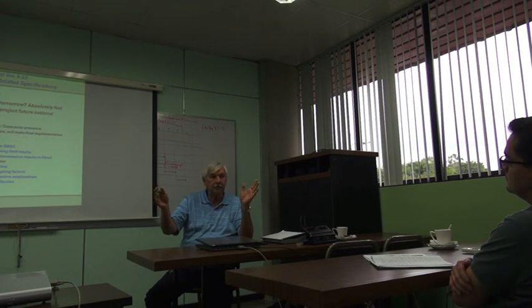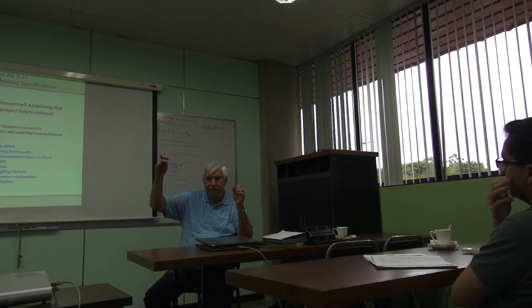Okay? If I wanted something that's going to last 20 years for fatigue cracking, I can convert what we actually build, the structure, into whether it's going to be 25 years, 15 years, 12.5 years. So eventually the final equation is going to be in terms of the predicted design life. Then the predicted design life is going to be a function of all of these things: the pavement structure, the E of the asphalt, the location, the temperature. The E in turn is going to be a function of the air voids, asphalt.